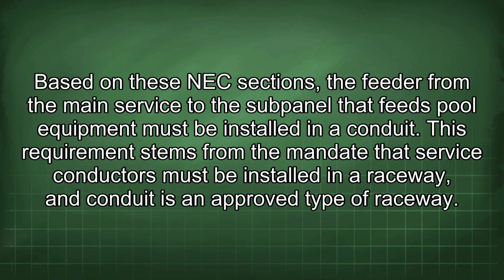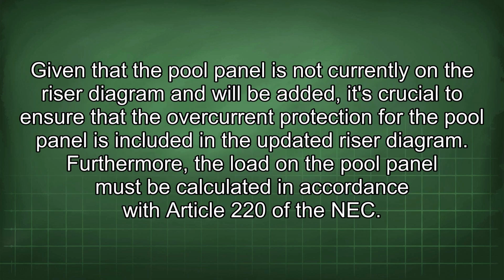Based on these NEC sections, the feeder from the main service to the subpanel that feeds pool equipment must be installed in a conduit. This requirement stems from the mandate that service conductors must be installed in a raceway, and conduit is an approved type of raceway. Given that the pool panel is not currently on the riser diagram and will be added, it's crucial to ensure that the overcurrent protection for the pool panel is included in the updated riser diagram.